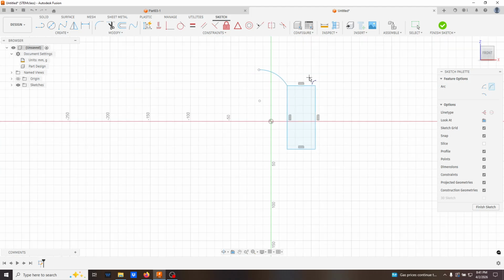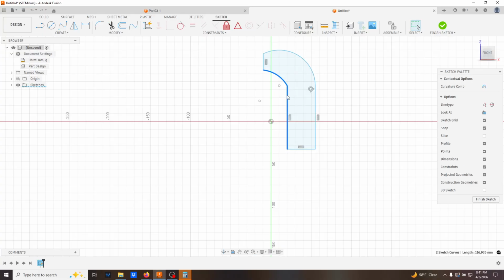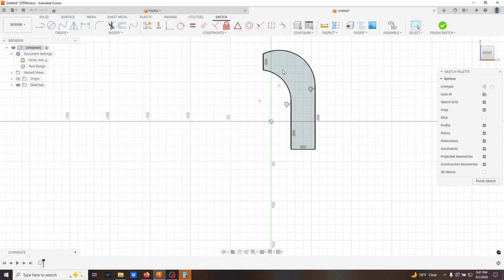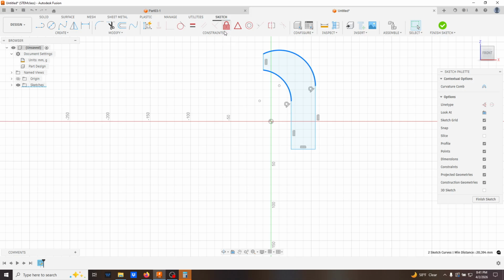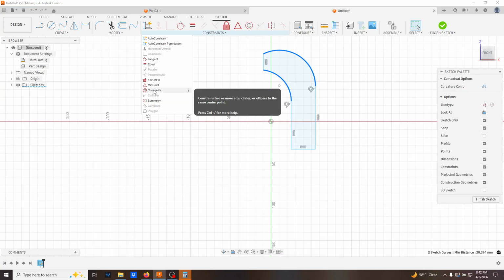All right, so we go zoom out a little bit. I'll go here. Now you'll see it gave me a couple auto constraints, and since I don't care as much, I'll just try to get it done. Let's go delete that. Oops. There we go. That button. Okay, then we go line. I'll turn the calculator on. Okay, line to here. Go ahead and I'll make this vertical, and then I'll make this tangent, and then this time I'll grab these two and I'll just make them concentric. There we go. And do the same thing.